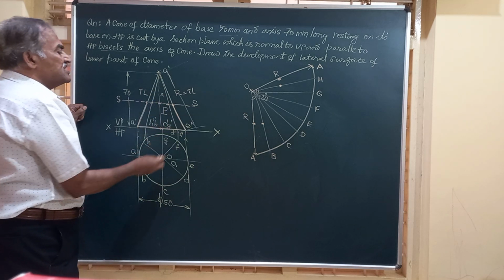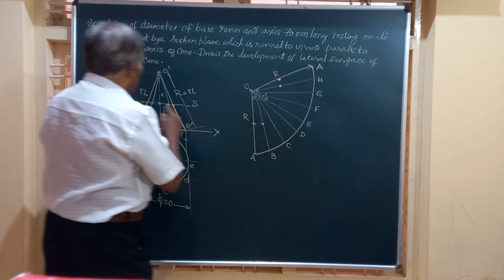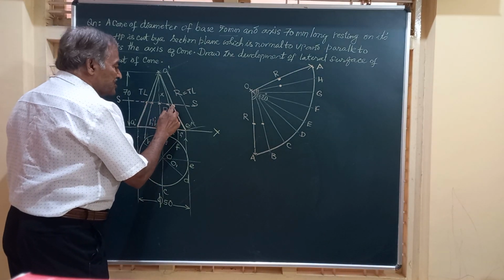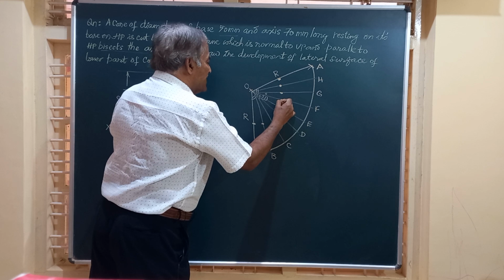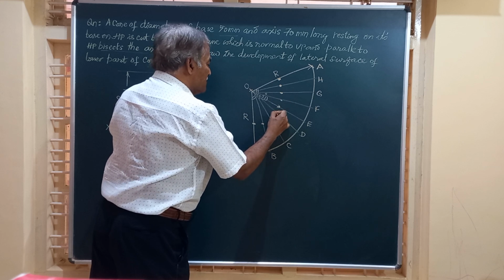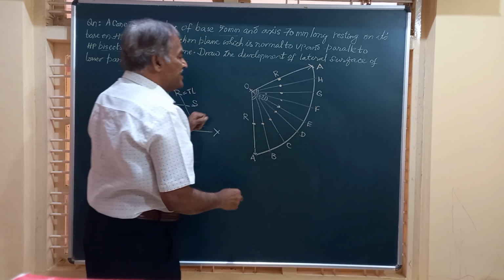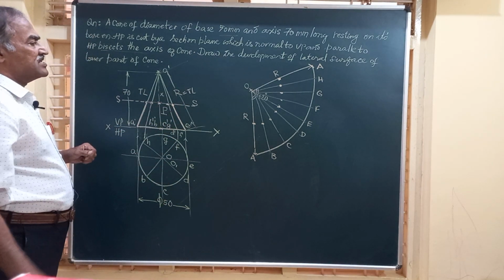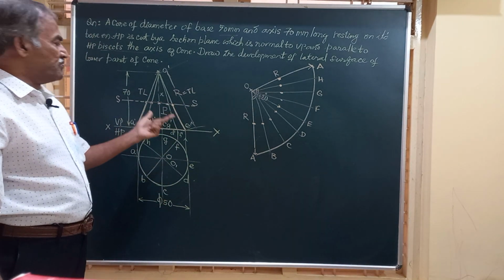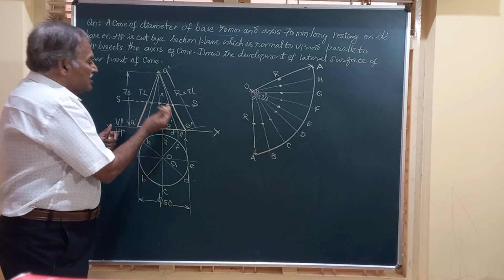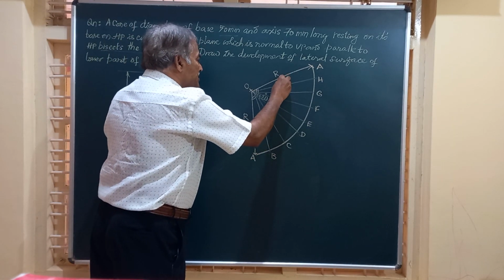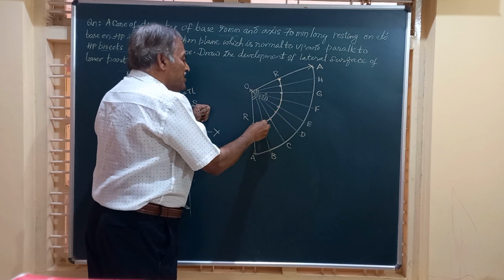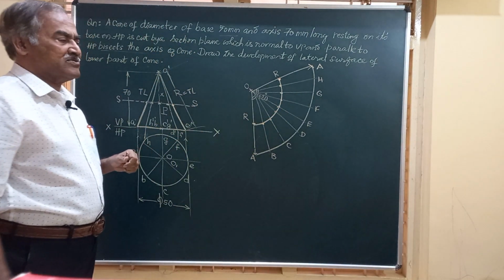All these generators are cut at the same height, and when we produce that to the last line, we are going to get all these points like this. So friends, on all the 8 generators, we have got the points marked because all are being cut at the same height. And friends, I am going to join the points so obtained by a smooth continuous curve.